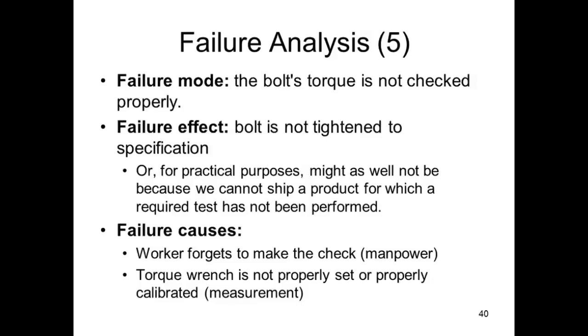The focus element or starting point is that the bolt's torque is not checked properly. The failure effect is the bolt is not tightened to specification, or for practical purposes might as well not be tightened to specification because we essentially haven't performed a required test. IATF 16949 also is very strong on things like traceability of information relating to the product, and also making sure that all of the required tests and quality checks have been performed.